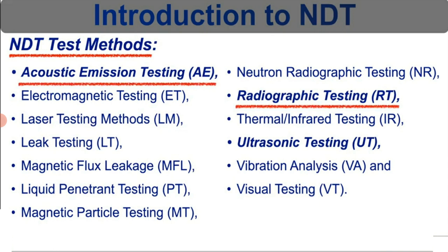We attach an ultrasonic transducer, which has both transmitter and receiver, at one end of the standard material with the help of a non-compressible liquid, and measure the total time elapsed for the ultrasonic wave to reflect back from the other end of the material.